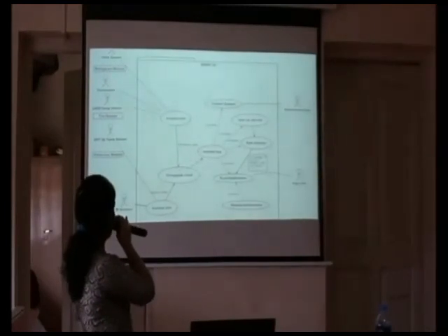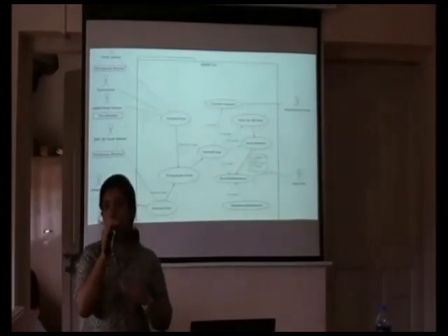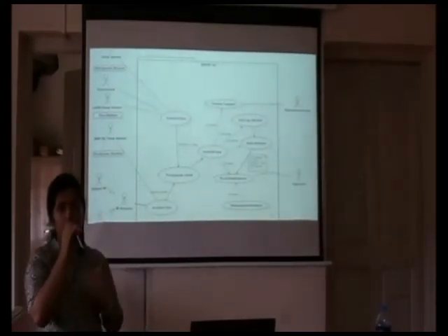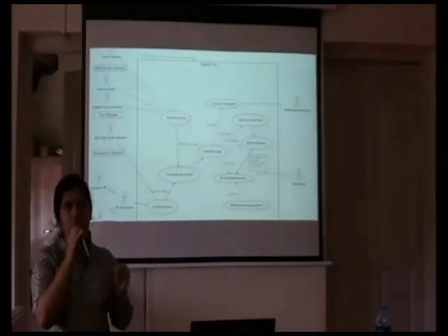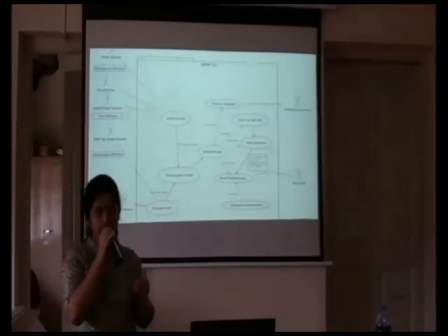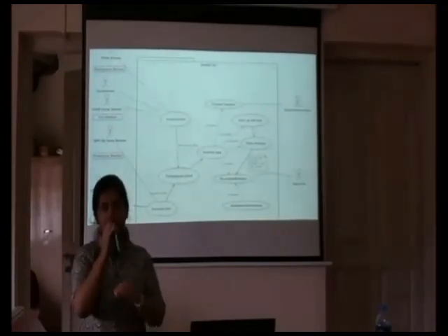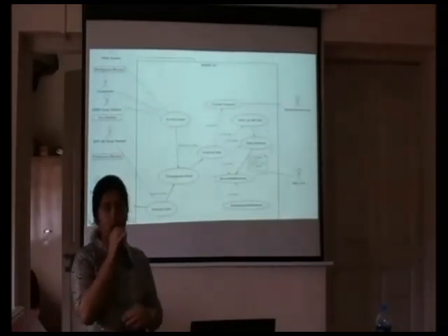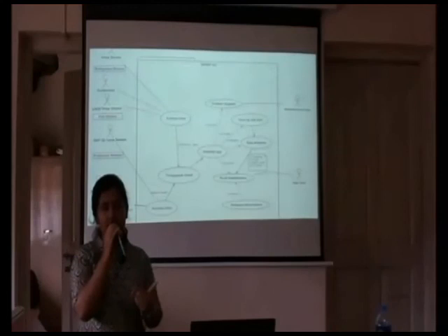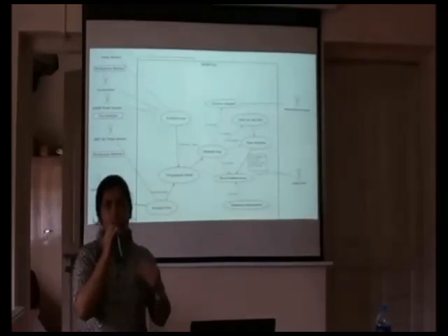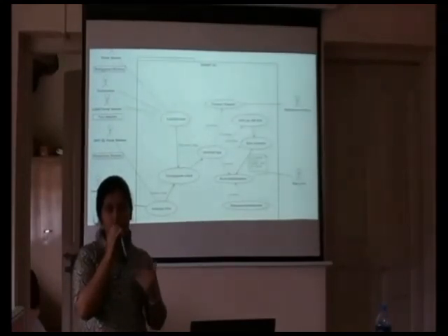Next comes the refrigerant module. The conventional method for determining the refrigerant level is by using a PT chart. But here what we do is place the temperature sensor in the suction line of the compressor unit. Then if the temperature is between 50 to 60 degrees Fahrenheit, it indicates that the refrigerant level is normal. But if it is greater than that, it indicates that the refrigerant level is lower and there are some leakage issues.